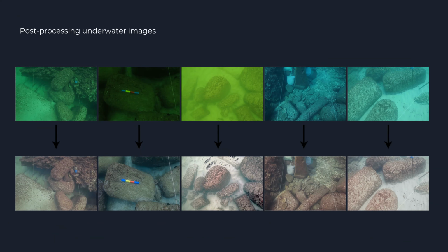Mohamed Said takes the photographs under the water, and I do the data processing, or post-processing, for the site. As you can see from the top image, this is the type of image color I got, because the visibility and conditions underwater are not at their best. Some days I got photos in light green, dark green, yellowish blue, or dark blue, and this was a challenge for most of us, because photogrammetry uses an algorithm that detects feature points, and it's better to have a homogeneous color so the software can recognize a photo, but sometimes that gets difficult.